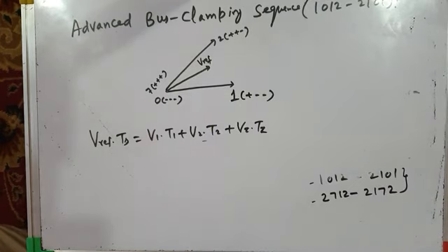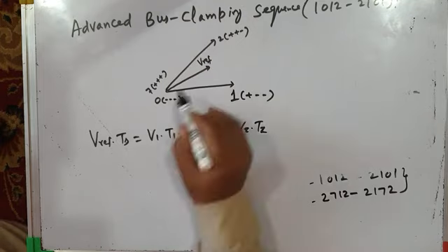We have already studied that, and that stator flux ripple results in distortion in the line current. And we will very soon in today's lecture study that the Q component of stator flux ripple is responsible for the production of torque pulsations or torque ripples or harmonic torques.